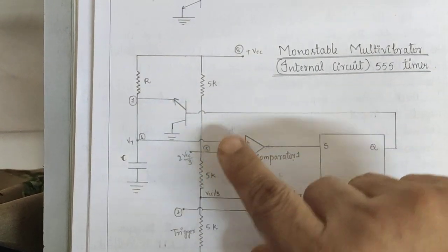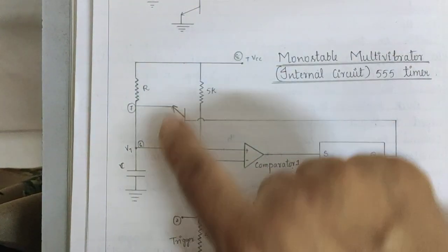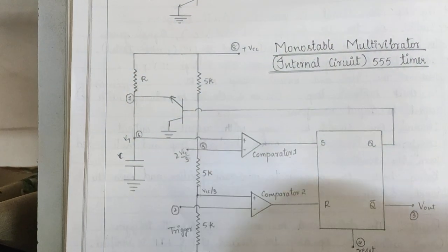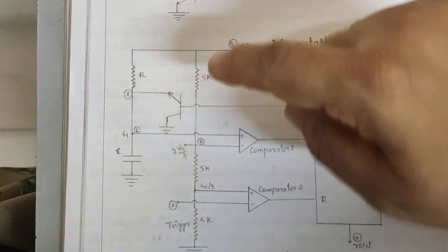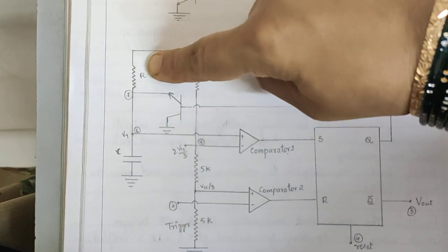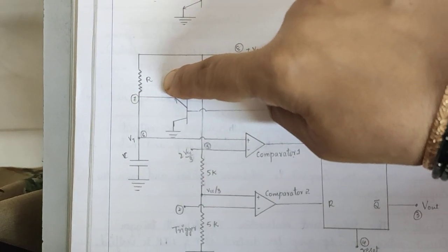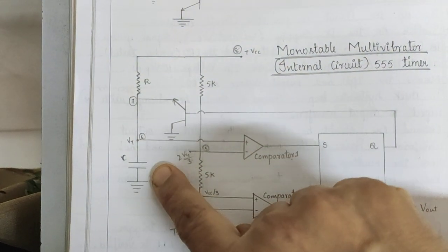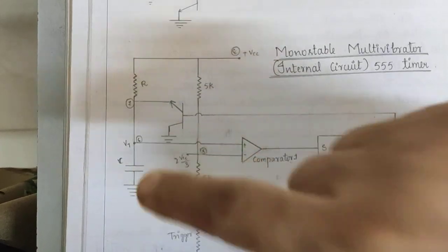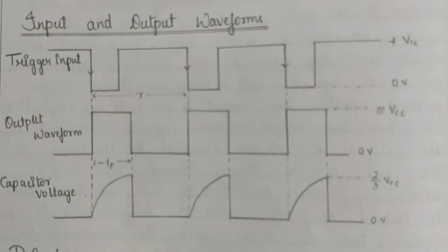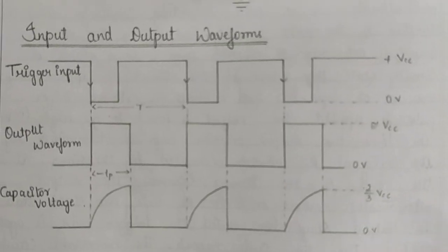Now you can also see this much will be the 555 timer, to which we have connected R and C. RA is what we had called the value as 10K and C as 0.01 microfarads. Let us view the input and output waveforms.